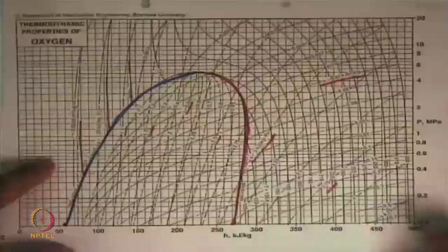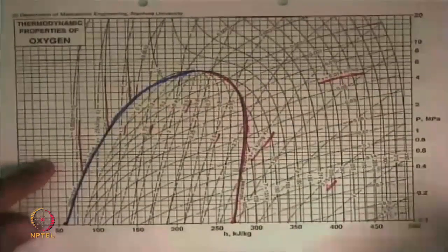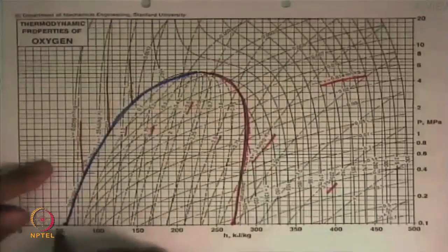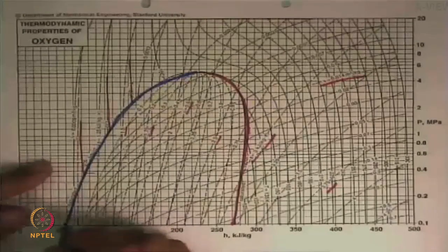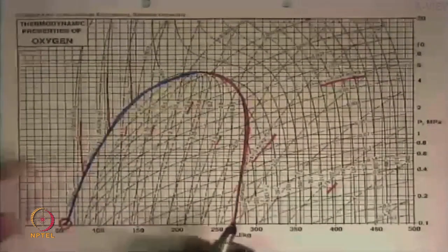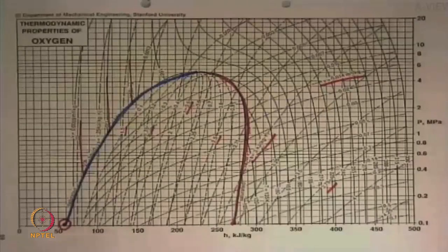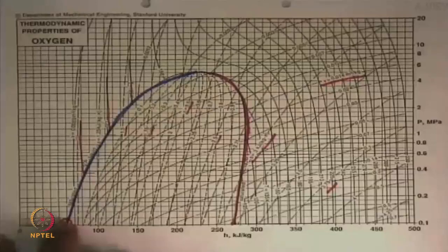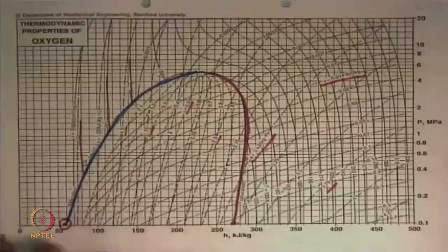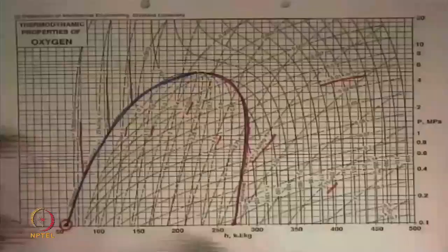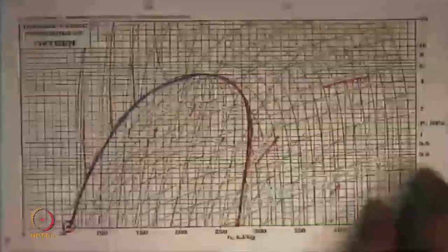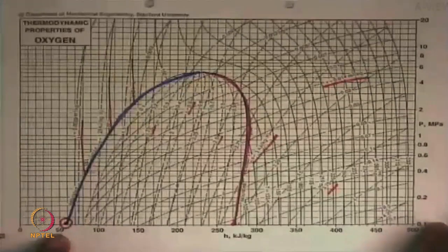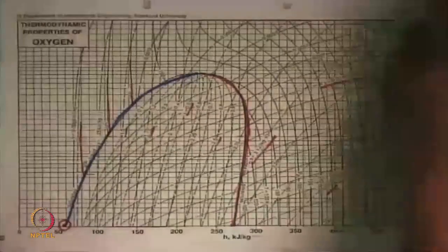And the reason for saying this is that in the cryogenic engines, a picture of which I showed you yesterday, the oxidant is liquid oxygen, which is filled at this state. So we need to know what is the specific volume there, how sensitive is it to temperature, what is the specific entropy, what is the pressure and temperature to which I need to cool it, and then we know how much volume we need to have in the solid rocket motor to put that much liquid oxygen in it. There are many other uses of oxygen.